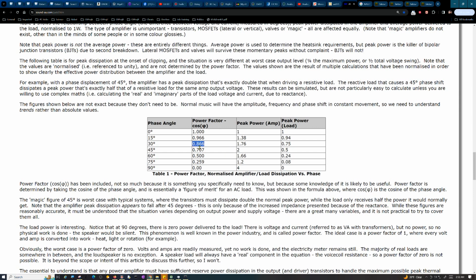Since that hot spot changes the beta of the transistor in that little spot, it causes thermal runaway to occur there, which will basically end up blowing a hole in your die, or giving it a meltdown. And that all happens very quickly, just like you discussed, within milliseconds. It can destroy your power transistor because of that peak power hitting that